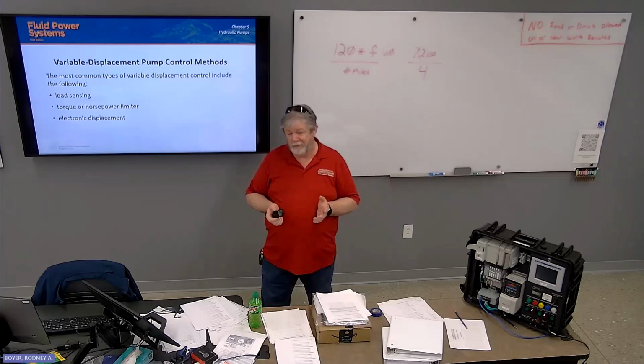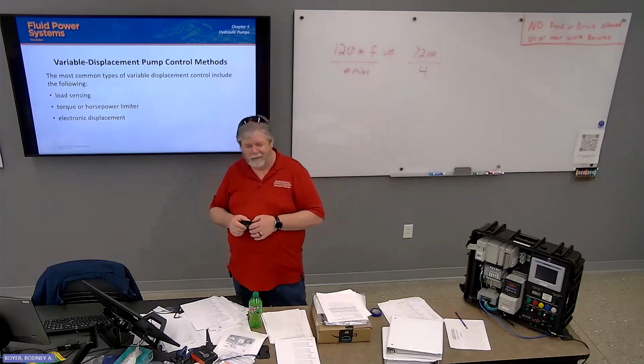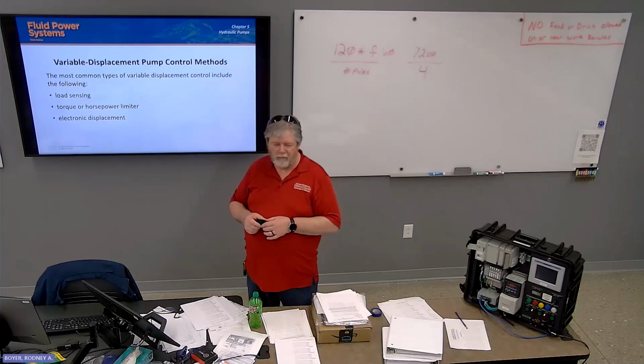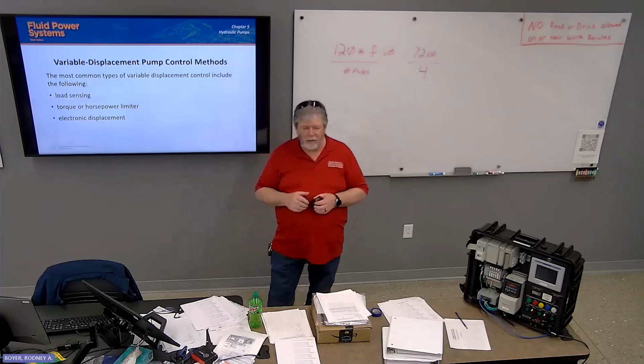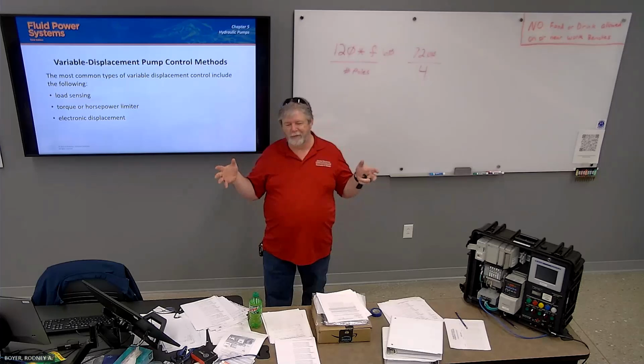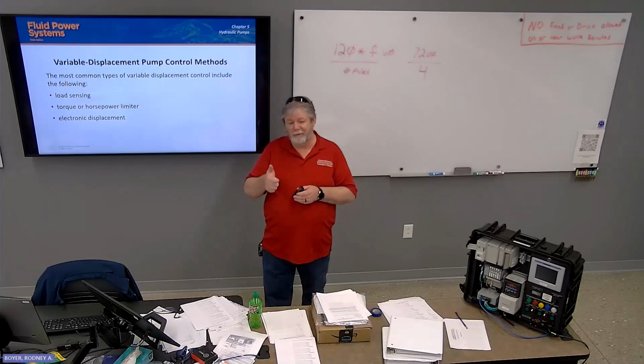Okay, that makes sense? Correct. So it's compensating pressure. Several other people are looking at me like, huh? What it's doing is compensating for the pressure drop when something's moving. It's compensating that pressure loss, so it raises it up. That's pressure compensation. When you allow the cylinder to move, you're actually increasing the volume in the system, and so in order to maintain the same pressure, you have to boost it up, give it more flow.